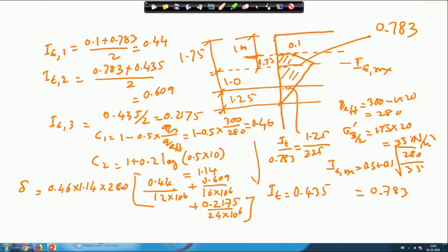This was a kilonewton. So, for that I can multiply by 10 cube, and then to express in millimeter another 10 cube. So, this will get cancelled. So, it will be expressed in millimeter, and if I simplify this entire thing, then finally, we will get total settlement equal to 12.3 millimeter. Okay. So, this is the one.